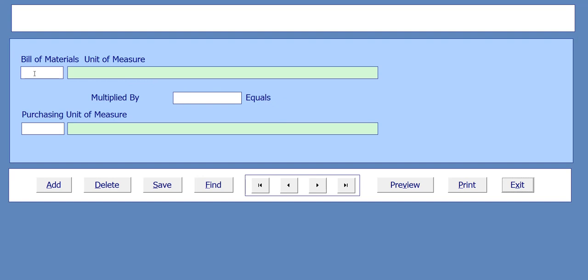So I'm going to type in, now this is only a drop down box. So if you haven't entered it into your unit of measurement yet, you can't actually do this step because you won't see what you want in the dropdown. But I already have it, so I'm going to go to square inches, and then I get my description in this thing. And then I'm going to choose my unit of measure. So I'm going to say SM1. So that's one sheet of 48 by 96.